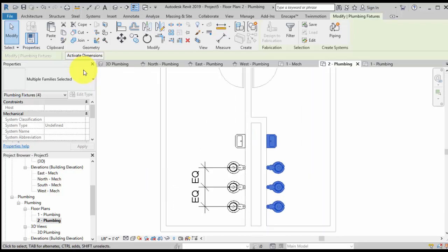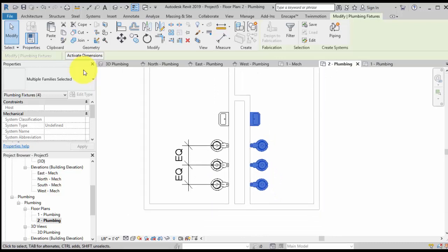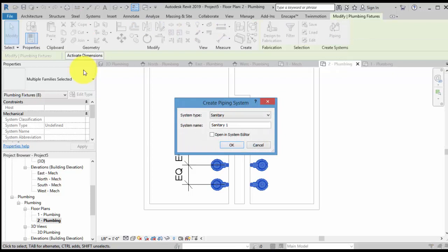We're going to select this. We can either select the whole thing, or select the plumbing and add them a little later. But what I'm going to do here is just select all of them now, because what's the point? Then we're going to collect the piping, creating the system. This is the time that we can change this to drainage, something we probably understand a little better. In reality it's called sanitary, but the piping system carries the gray water away.